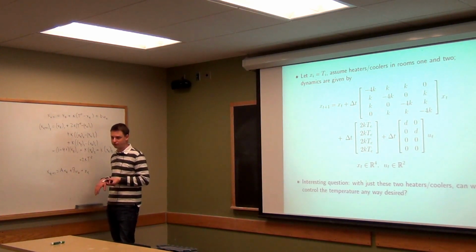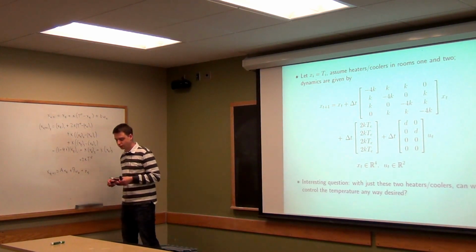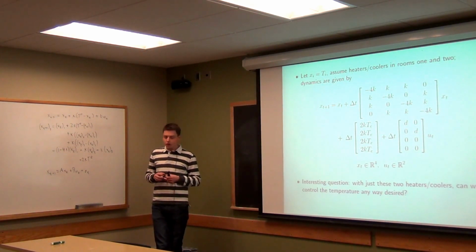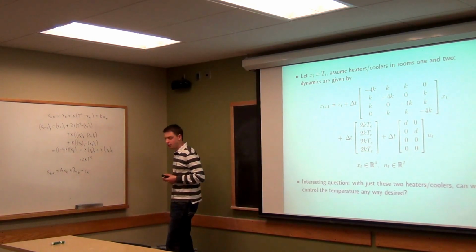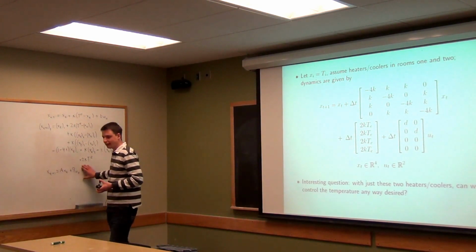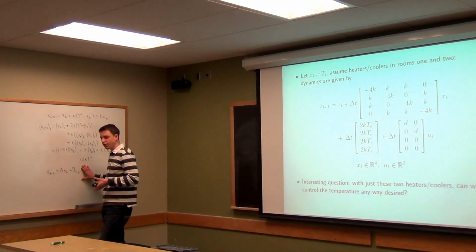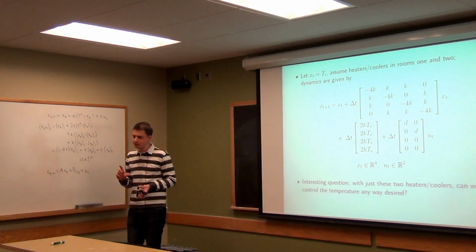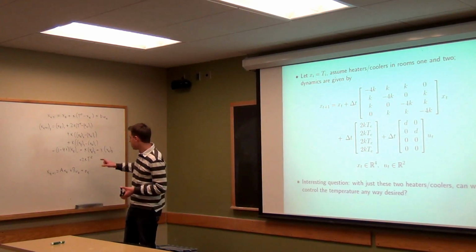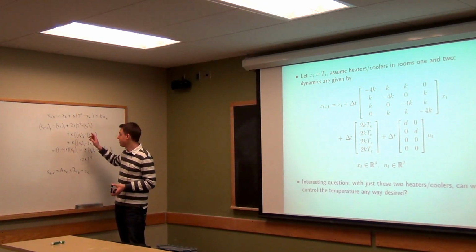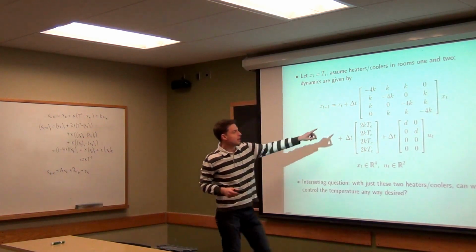But for example, maybe we can treat the temperature difference between internal and external... Yeah, you could certainly do that too, and then make delta t be your state, and that would result in a linear system. Absolutely. So if your state corresponded not to the absolute temperature but to the actual difference in temperatures, you could do that. The tricky thing there is that the actual equations are a little trickier to do there, because you have a term.